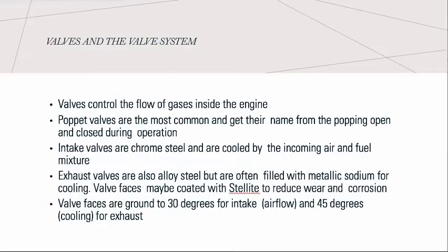The motion of the engine valve is driven by the camshaft of the engine, which contains a series of lobes or cams that serve to create linear motion of the valve from the rotation of the camshaft. The intake valves on internal combustion engines are subject to less thermal stress because of the cooling effect of the incoming air or fuel mixture that passes by the valve during the intake cycle. The exhaust valves, by contrast, are exposed to higher levels of thermal stress by being in the pathway of the exhaust gas during the exhaust cycle of the engine.